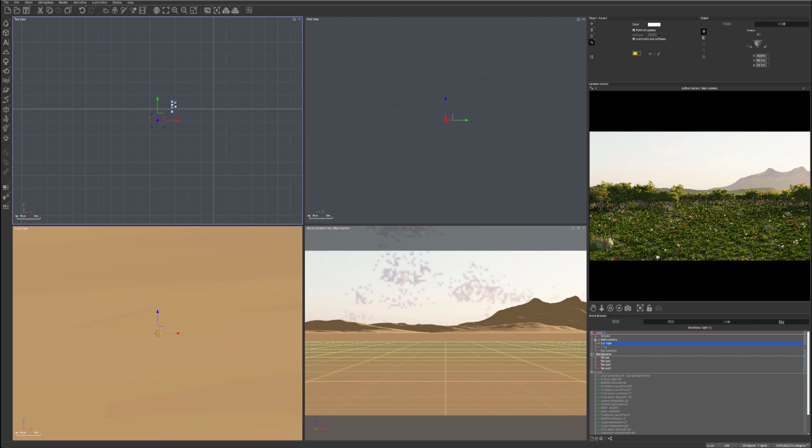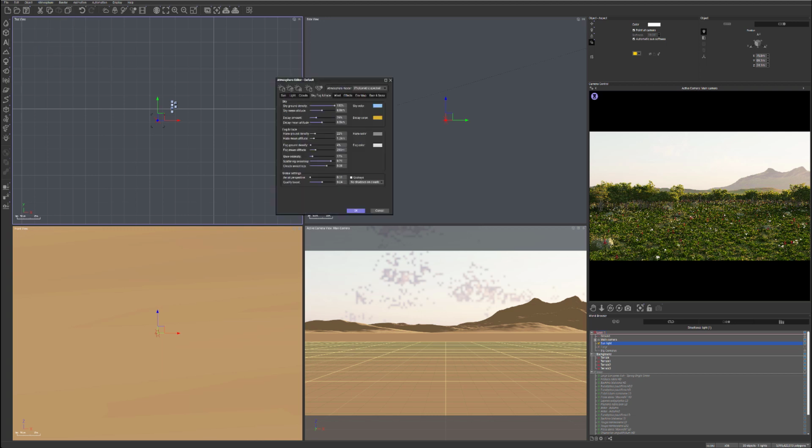Okay, so let's go to the atmosphere editor right now, and in the atmosphere editor we're going to work a little bit. Notice we work in photometric spectral. So in the photometric spectral, let's try to create this accurate look, but with this we're losing some saturation, the illustration colors. So we'll continue working with this set, but we'll need to add clouds.